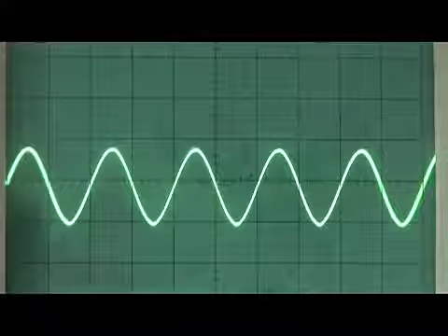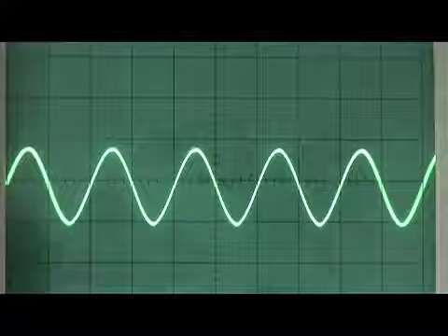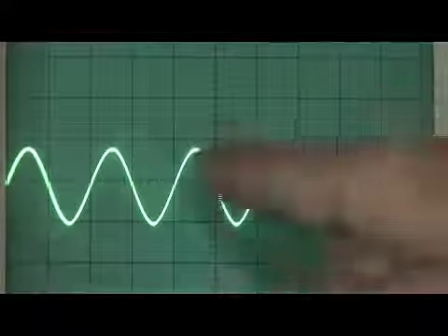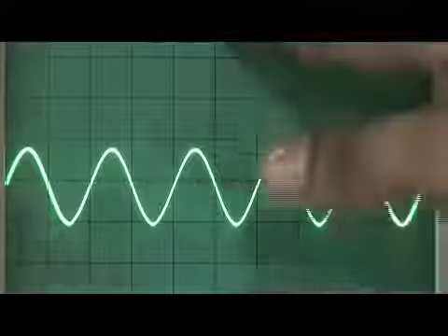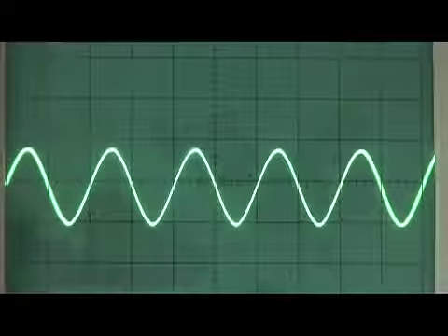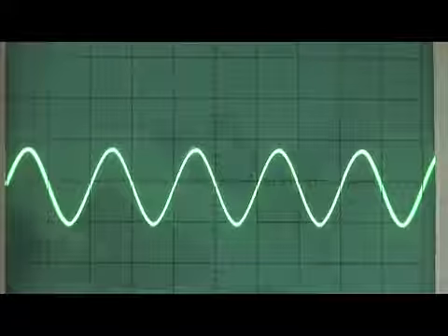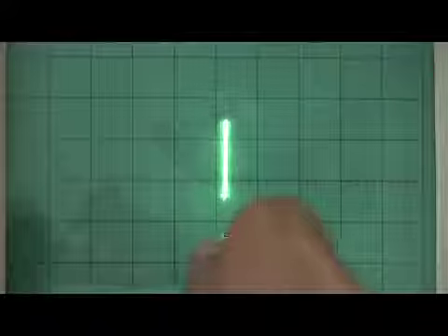Now we have to calculate the amplitude and the frequency of this signal using this CRO. Because the amplitude is always in the y direction, I can use this XY, because I am interested only in the y direction, not the x direction. When I press XY, it suppresses the x-axis, since I am only interested in the y-axis. You can see that it is properly coming from here to here. Now, this dark black line, which has subdivisions, is your reference line. Using this y position knob you can move the line and bring it over here so that you can properly count the number of divisions.